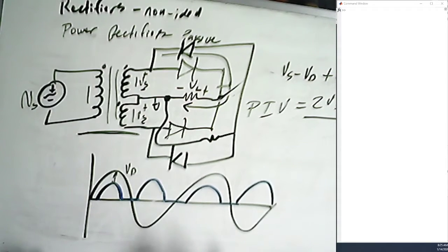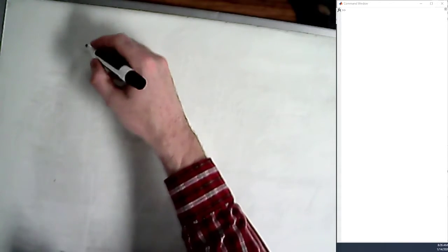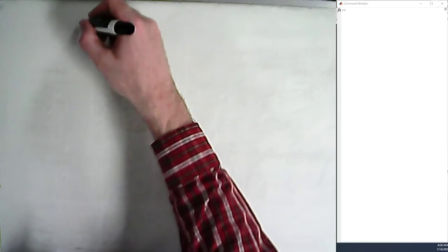So those are our 3 passive rectifiers. All of them have this problem, but there's no way that we can get by that if we want to do power. So power, we're trying to convert one form of energy, typically AC to DC, with all of these. And so what we need to do next is worry about what's going to happen if we really care about that 0.7 volts, as sometimes we do. And this is a little bit down the road, but let's take a look at this. So this is what I call the signal rectifier.